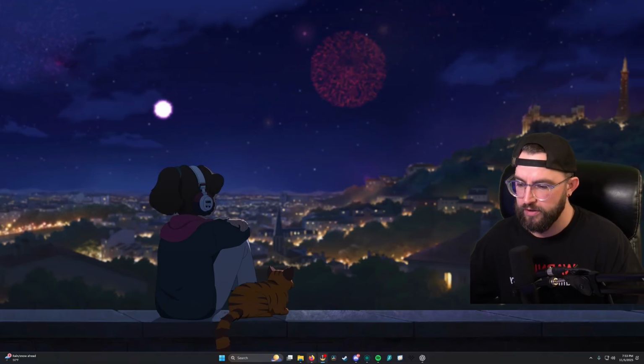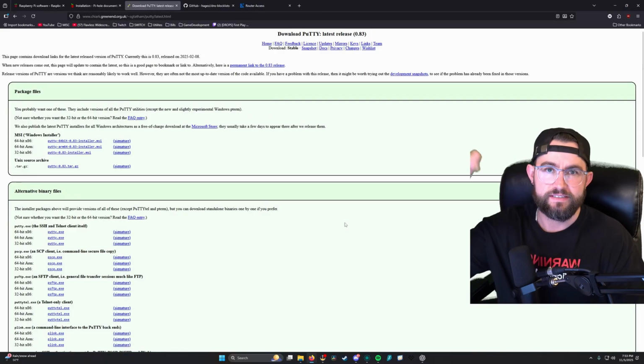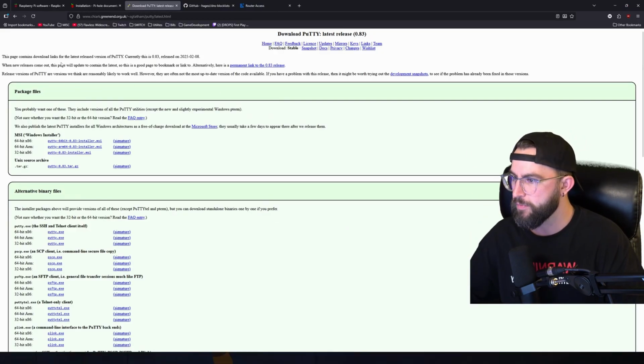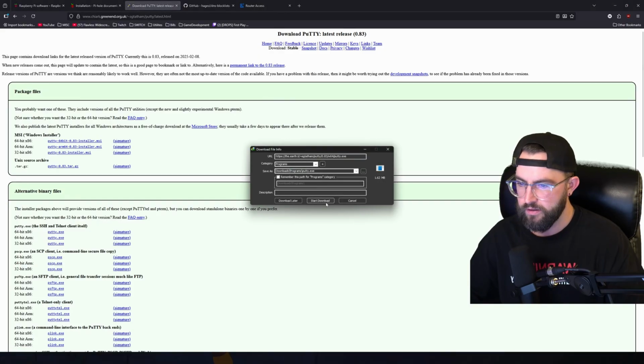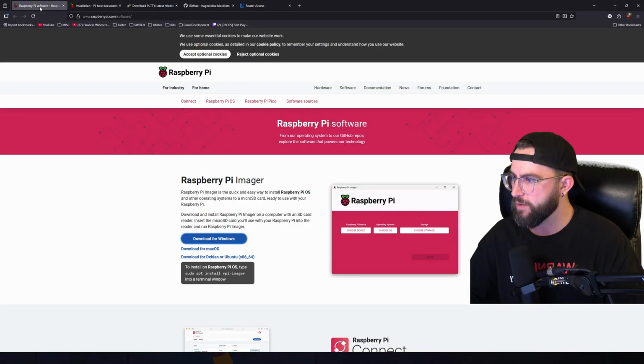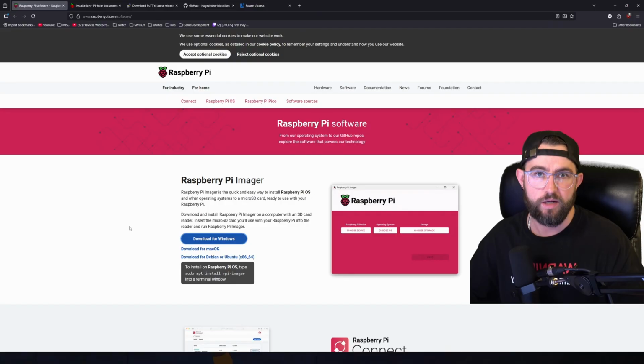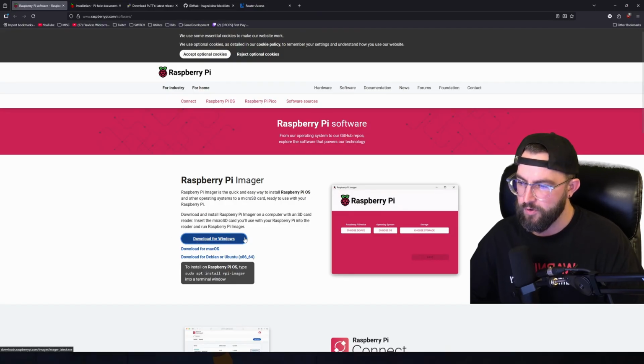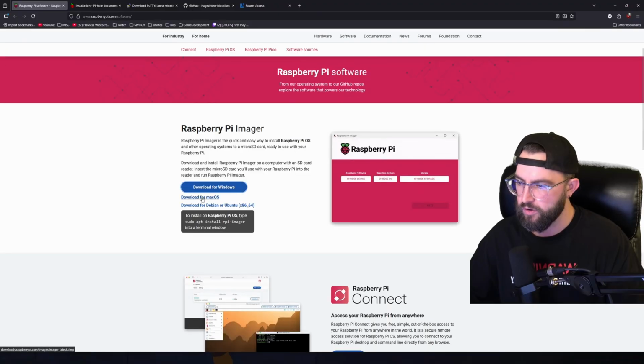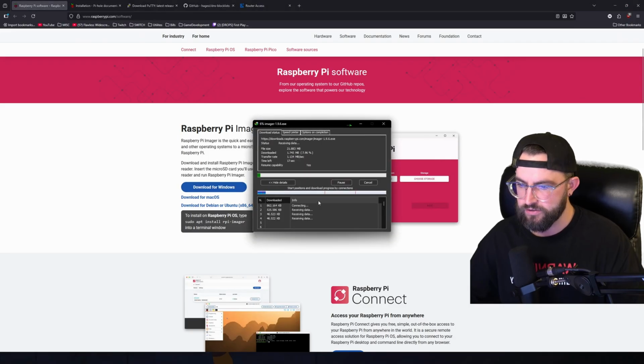The next thing we want to do is come to this website here. I'm going to have all these links down in my description so you can easily follow along. We're going to come to the PuTTY website and download PuTTY, the 64-bit. I'm going to grab the putty.exe and start the download. I'm also going to come over to the Raspberry Pi website, and this is the Pi Imager that allows us to create the operating system for the Raspberry Pi. I'm on Windows, so I'm going to grab the Windows file, but if you are on Apple, you can do the macOS version here. And if you're running Linux with the Ubuntu distribution, you can grab that here. Again, I'm on Windows, so I'm going to grab the Windows one and hit start download.